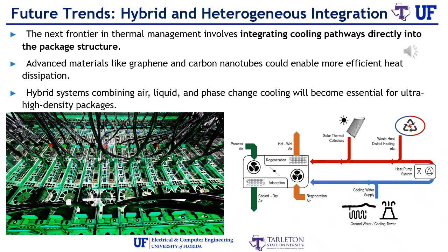At the same time, packaging architectures are evolving. Concepts like microfluidic cooling channels, self-regulating liquid loops, and hybrid air-liquid systems are moving towards practical use. We may soon see packages where coolant flows directly under the hottest blocks or where phase change materials are integrated at multiple levels to smooth out temperature spikes. As the industry moves towards chiplets and denser 3D stacks, thermal design will be central to system architecture and not just an afterthought. In summary, effective thermal management ensures that advanced semiconductor devices can deliver high performance safely and reliably.